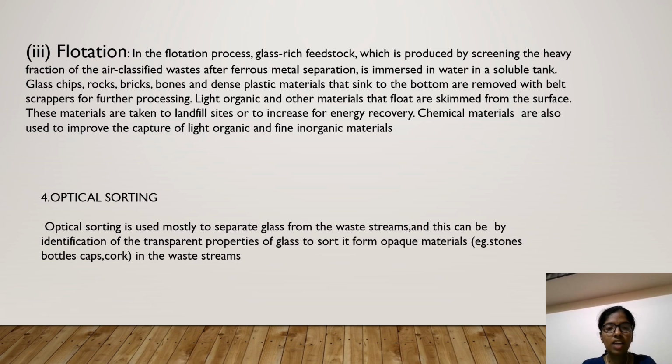Flotation is a process applied to a glass-rich feedstock, which is produced by screening the heavy fraction of air-classified waste after ferrous metal separation, in a water-filled tank. Glass, rocks, bricks, bones, dense plastic materials and chips that sink to the bottom are removed with a belt scraper for further processing. Light organic and other materials that float are removed from the surface. These materials are taken to landfill or used to increase energy recovery. Chemical materials are also used to improve the capture of light organic and fine inorganic materials.